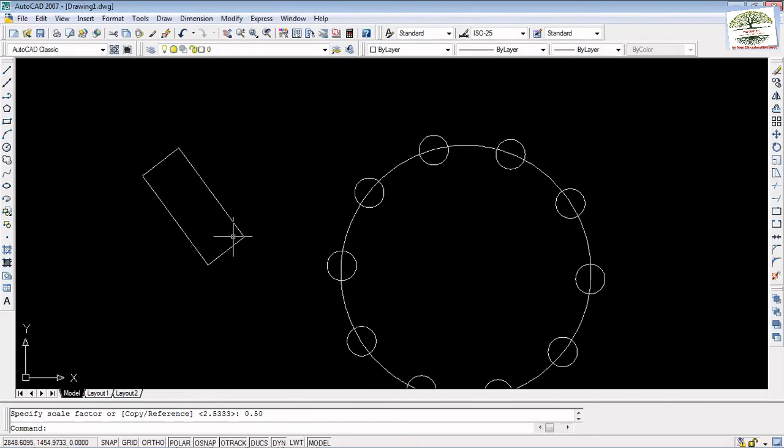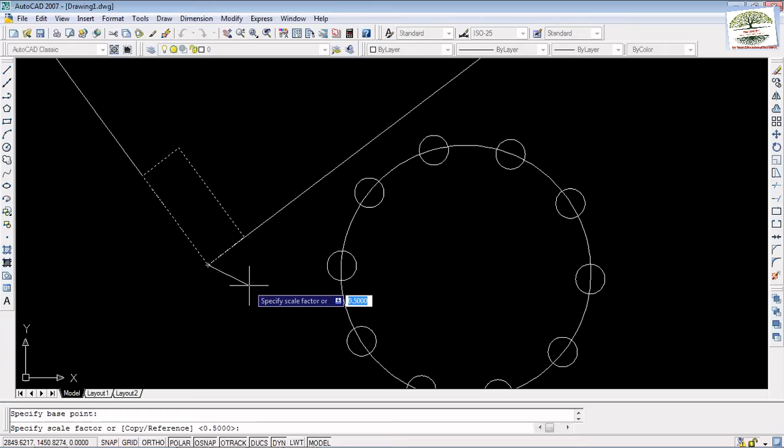Reduced. Again, if you'd like to reduce, SCALE, space bar. Select, left click, right click. Now I have to select the best point, obviously. So I've selected the best point, and I'd go for 1/4, 0.25, in the whiteboard, written, space bar.